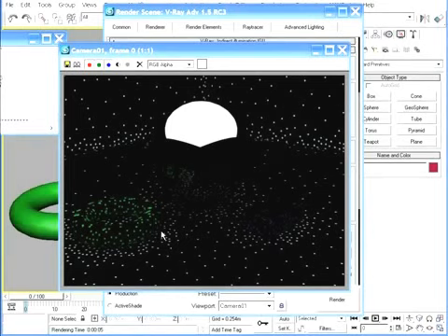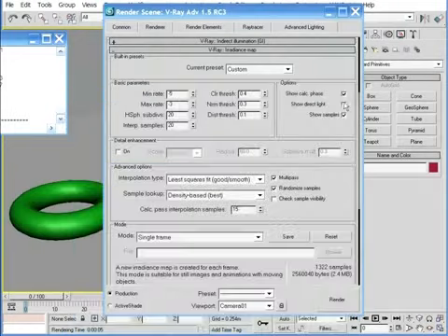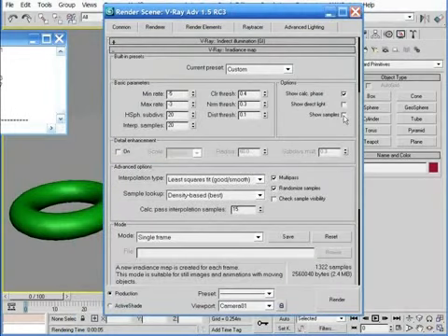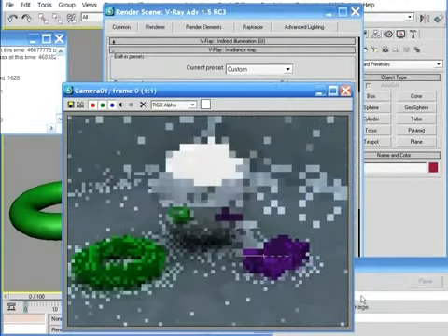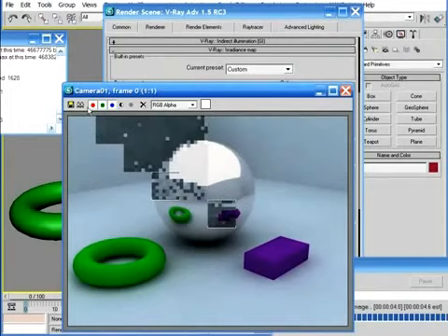And so it's this adaptive quality of the Radiance map that makes it so great. The ability to be adaptive to each particular scene and apply more sampling in areas where detail is needed and less sampling in areas where detail is not needed. So let's render the scene out with a minimum rate of -5 with the show samples option turned off, and see what kind of quality we get, and compare it to a minimum rate of -3.